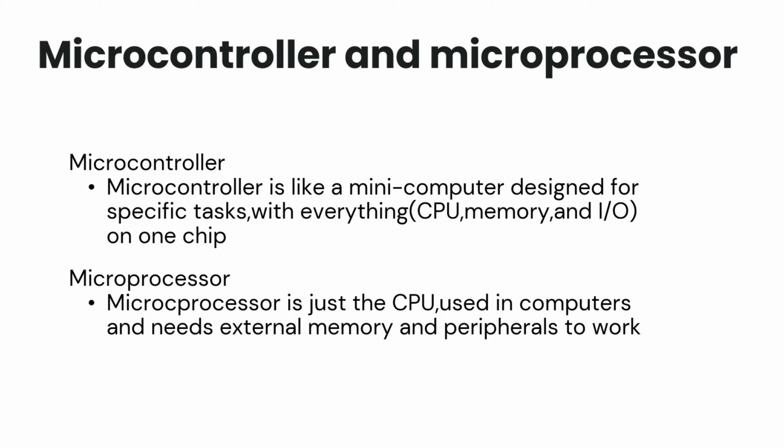The CPU is the core of the microcontroller and is responsible for executing program instructions. It performs arithmetic and logical operations, controls data flow, and manages communication between different internal blocks. The CPU operates using a fetch, decode, and execute cycle, where it continuously fetches instructions from the program memory, decodes them, and executes the required operation. The speed of execution depends on the system clock frequency, which provides timing synchronization for all internal operations of the microcontroller.